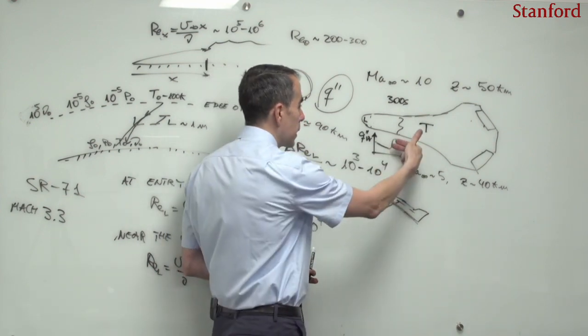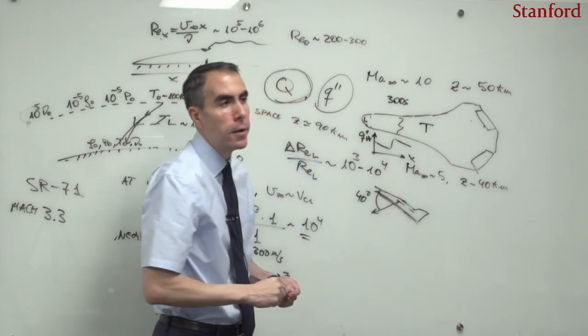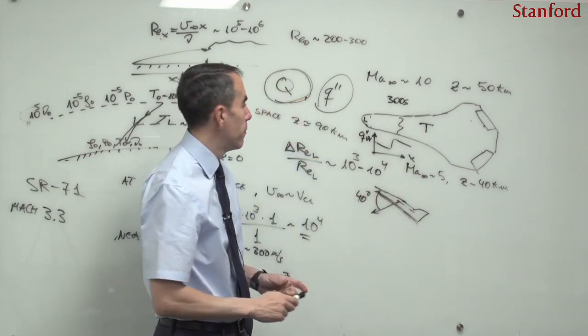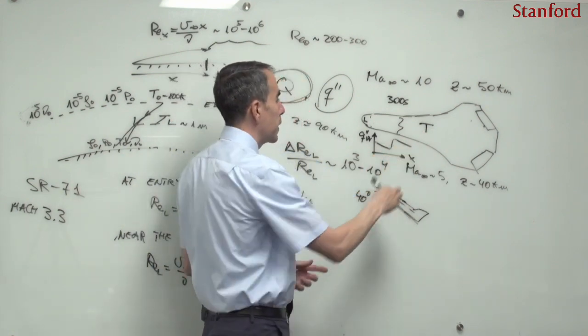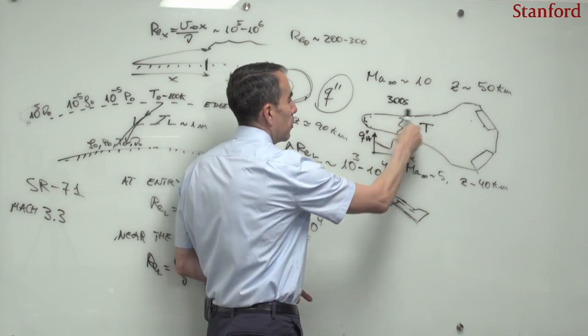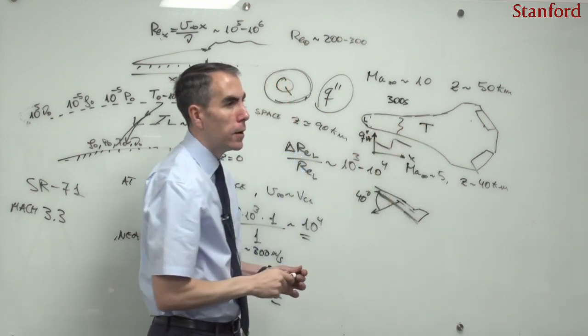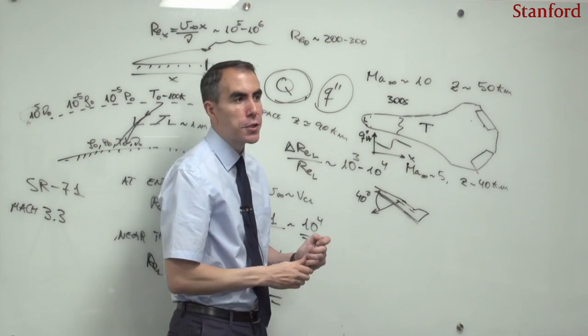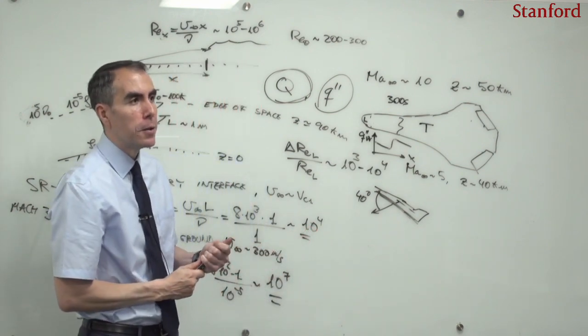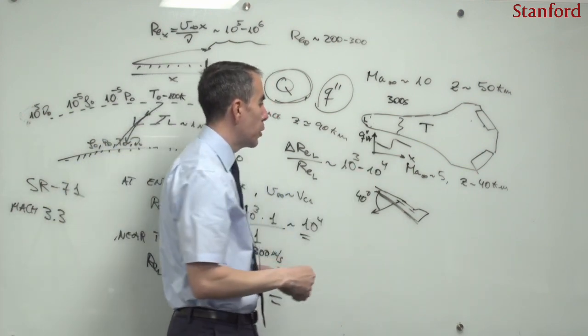But the truth is that here there will be a jump in the heat flux that will be significant, and on top of that, this peak is moving along the underbelly. So that causes concerns in prediction, and this problem is still open.